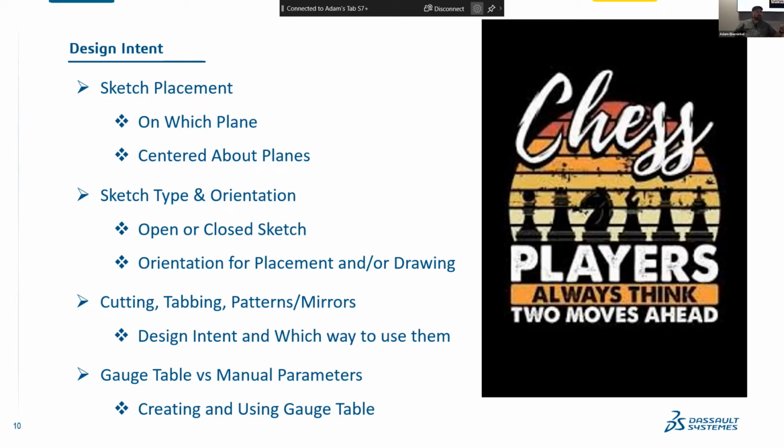I'm going to get into gauge tables just a smidgen here. I do have a presentation coming up later this week that is the advanced sheet metal part of it, and I'm going to get more into gauge tables there. They're very easy to use and they make for consistent drafting, right? So no matter whether you use something a certain way and say you want 12 gauge at 0.105, and the next guy down here says he wants 12 gauge at 0.0555, whatever you're getting from your vendor, maybe they're going to the next decimal point, and those decimal points can add up, right? And so if you have a gauge table, everybody's selecting it from the same thing.